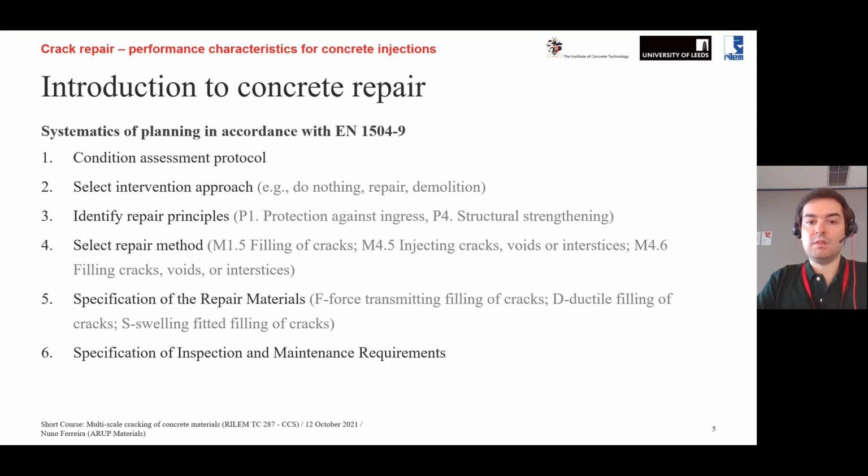Again, doing nothing, is it the repair, is it the demolition? Once this is defined, we can start to identify the repair principles, assuming we are repairing. The repair principles, and I only listed the ones associated with injections, are the protection against ingress and the structural strengthening.